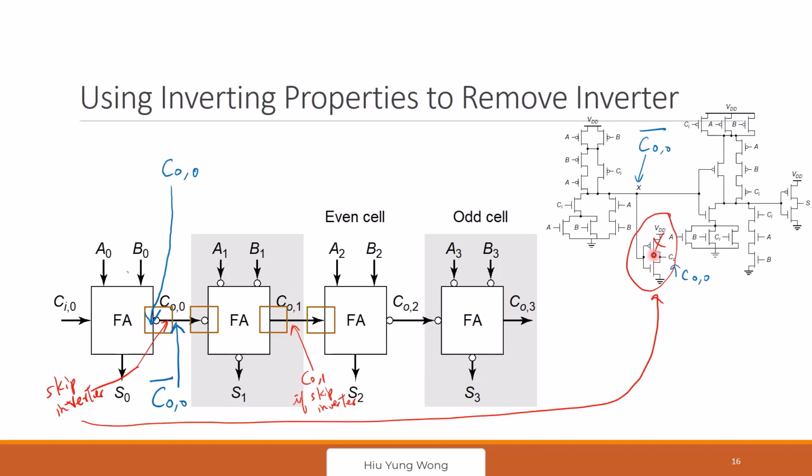Professor, I had a quick question about using the even and odd cells. Because we're inverting each of the inputs, wouldn't that add a significant amount of delay? Oh no, never mind. Good point. Here it's just showing that we invert it, but in the real implementation, after we add the inverter, we see that we have 2 inverters. We just don't implement them. So actually you save it. Is that what you understand? I was actually talking about the inverters on A and B, and then S. Oh, very good. That is also very good.